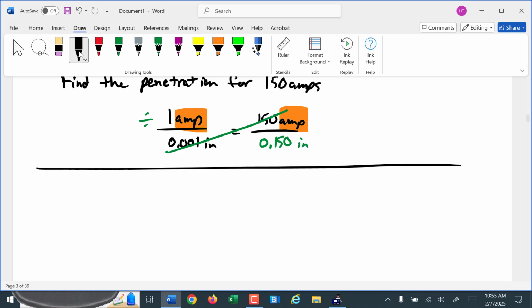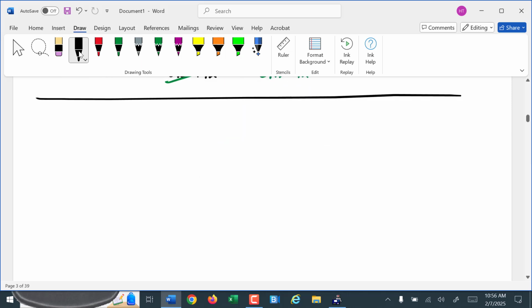So as we're dealing with metallurgy, one of the other important quantities describing metal is something called an elastic modulus. It describes how much a metal is going to stretch or compress under a given force. To understand elastic modulus, though, there are a couple of things we need to talk about. First, one is stress. The stress on any sort of a support member is the load over the area that it's applied, often called a cross-sectional area.